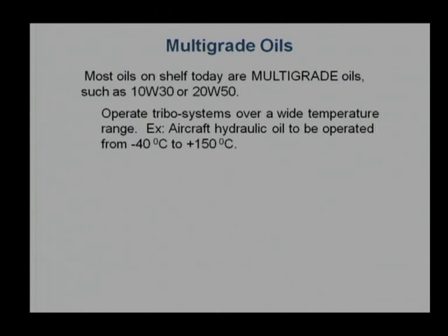Continuing with the mineral oils: not very high VI, not very high viscosity index, more tendency towards oxidation at moderate to high temperature. We use multi-grade oils. Main ingredient is a mineral oil, but what we are trying to do is some sort of hybridization. Maybe one lubricating oil is good for low temperature application, another is good for high temperature application. We want to hybridize to come up with a lubricating oil that is good for low temperature application as well as high temperature application.